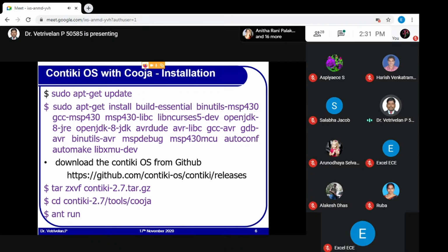And if you see the overall stack, we have Zigbee with the 802.15.4 physical and MAC layer. On top, we have 6LoWPAN, that is the adaptation layer for IPv6 support, and for routing support, that's RPL, with IPv6, UDP, and CoAP transactions, CoAP methods. That's what we are going to see here. CoAP comes under application-level protocols.